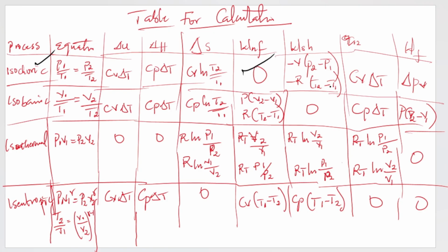If you are given a value for your shaft work in your question, you simply recall these two equations, because any value you are given for your shaft work will have a negative value, due to your formula for shaft work. But if you are not given any value for your shaft work for a particular system, and you know that system is a rigid system, you are taking the shaft work to be 0.